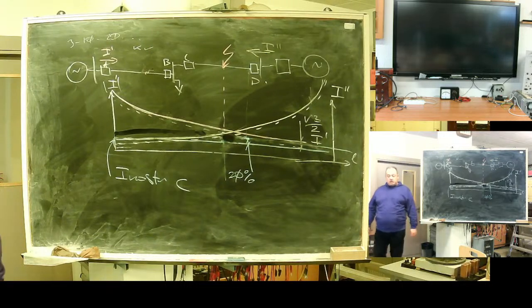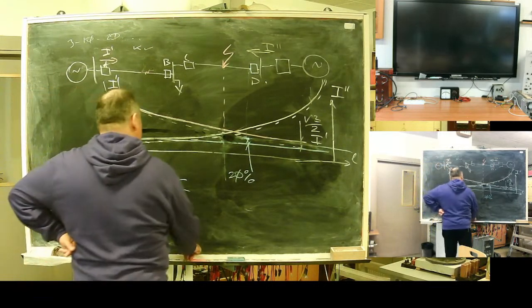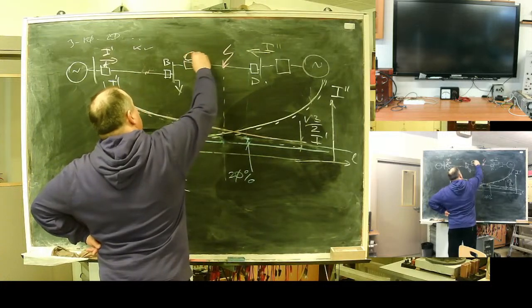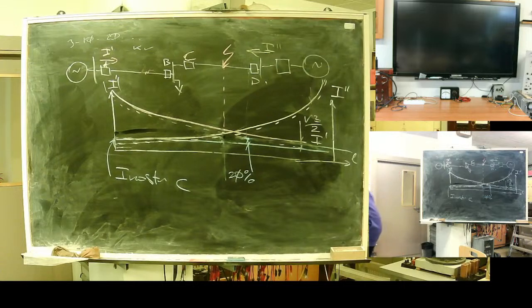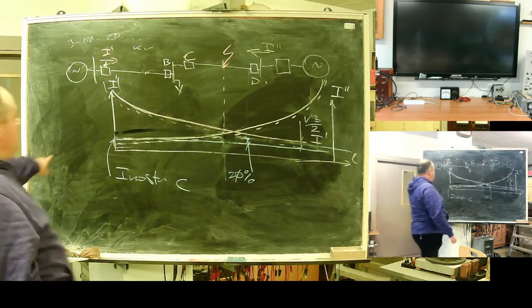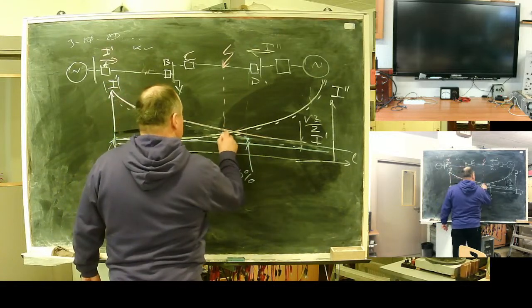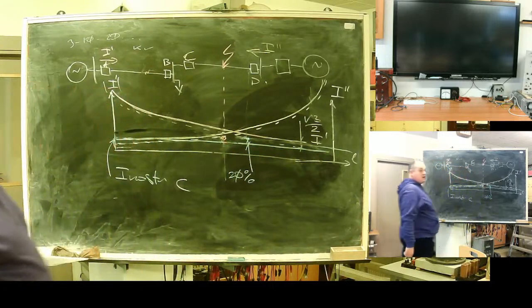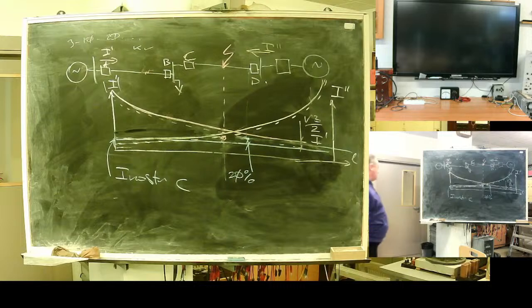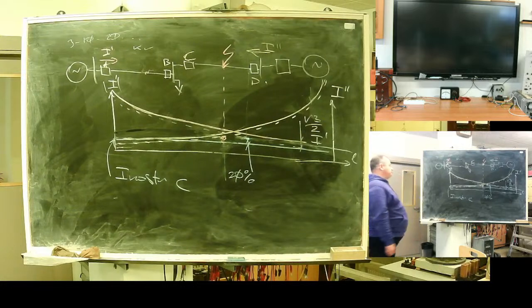We got the distribution network powered from both sides here. And this nice relay, I draw here is the trip current, and here is the current of my fault, and you can see that if the fault is above the trip current, the relay will send a disconnection signal to the switch and the fault will be cleared. Very nice.